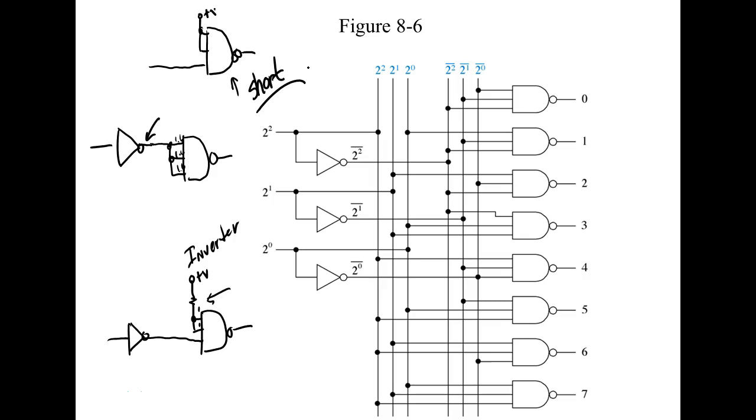The power supply kept cutting off. And what happened is an input to a logic gate shorted like that. This board had about 100 integrated circuits on it. And why? Because the engineer didn't put a pull-up resistor on the inputs of unused gates.